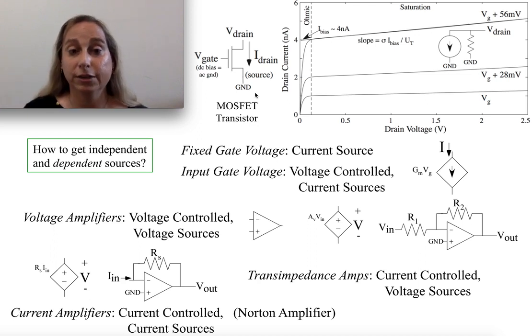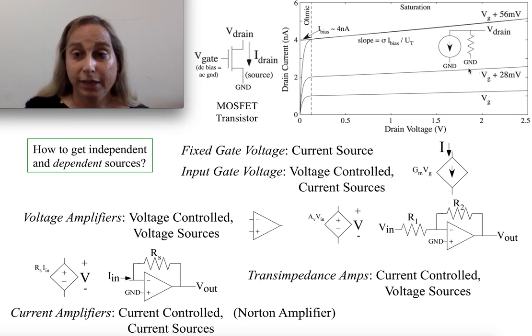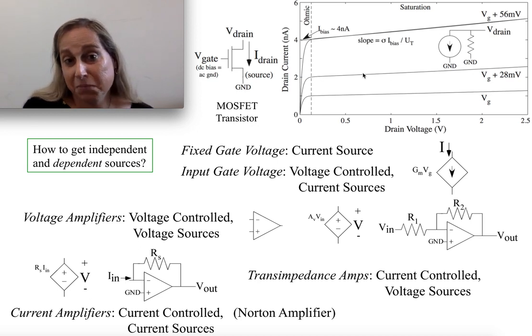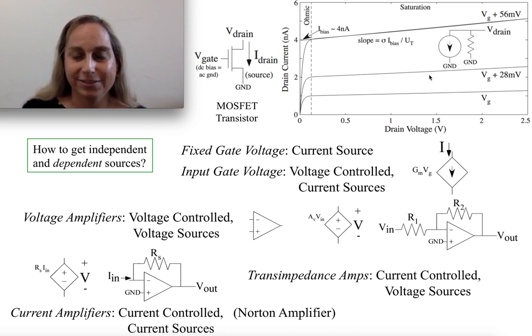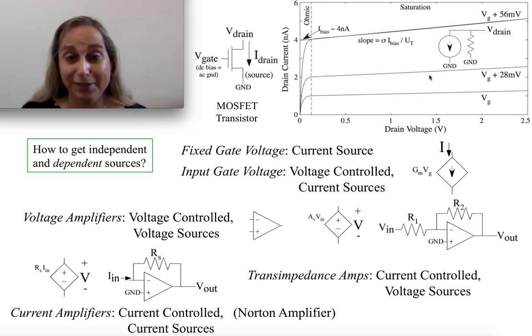And again, it's true for the linear part of the operation that you're going to expect to see something like this. Now, in practice, transistors aren't perfect, and you would end up finding there's some slope to these things, and we can talk about the slopes and their various relations. One way that people might model a single transistor to ground is that you might have a resistor in parallel with it, because at least at one level of looking at the data, it kind of looks constant. So that kind of works. Okay, and so now I get multiple linear elements. This is, of course, a nice Norton equivalent circuit for this.